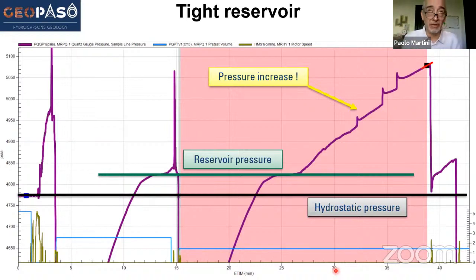There's microfracturation going on, and even if your packer is correctly placed on the formation, maybe hydrostatic pressure gets through this microfracturation to the probe, and it compromises the seal. So that's what I think is the most important effect on the acquisition, not on the pressure data itself.